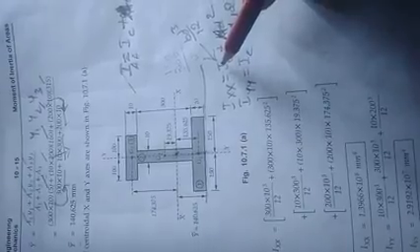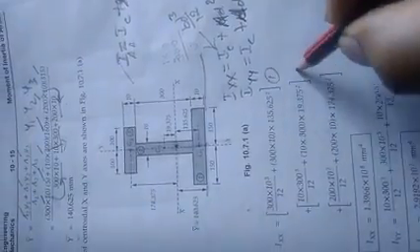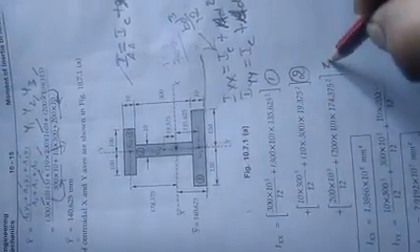What you have to do is take this formula. IC is the centroidal moment of inertia, about the centroidal axis. Use the formula BD cube divided by 12 for a rectangle section. B is breadth, so breadth is 200, depth is 10. This is the first section, this is the second section, and this is the third section.